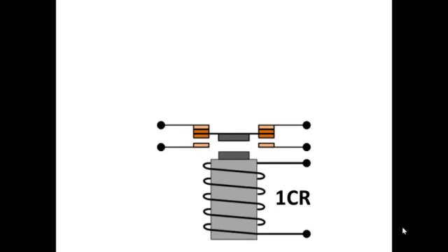So here's our new contact relay, no longer with a common, which means that the normally open, which you see open right now, and the normally closed, which you see closed right now, could be used in 2 completely separate circuits because there's not just one common contact for both. So right now, the normally closed is closed. So if you query this relay coil to see if it's energized, the normally closed contacts are closed, and they would have continuity indicating that the relay is de-energized.